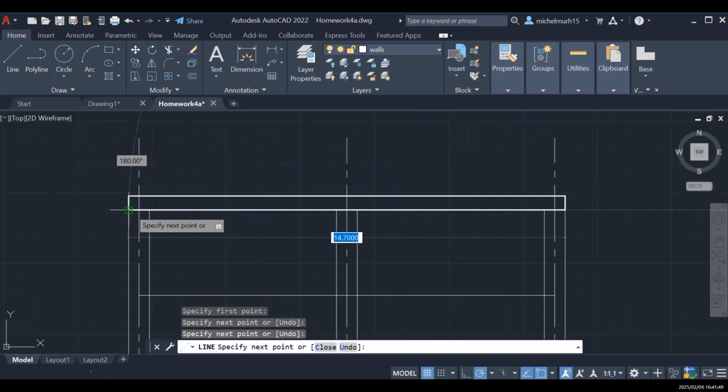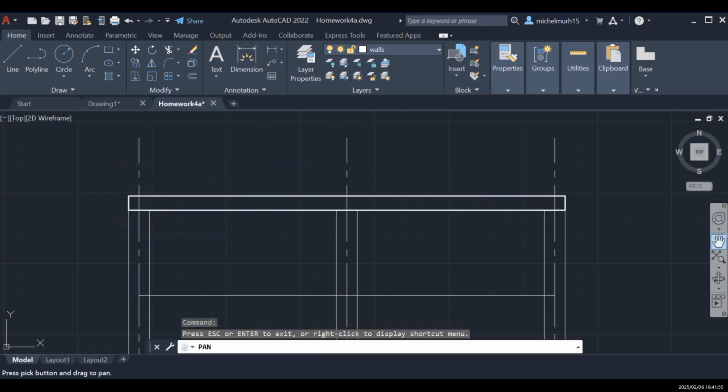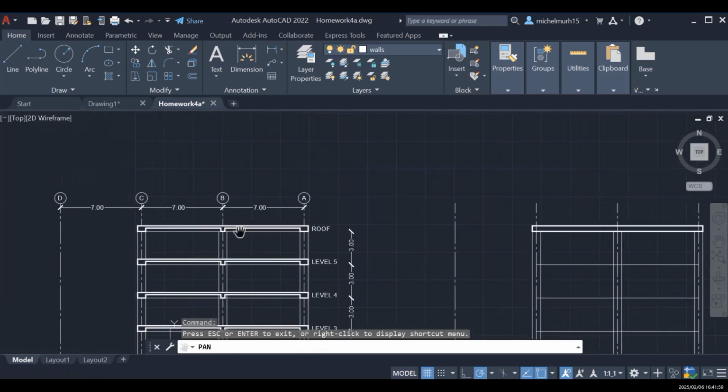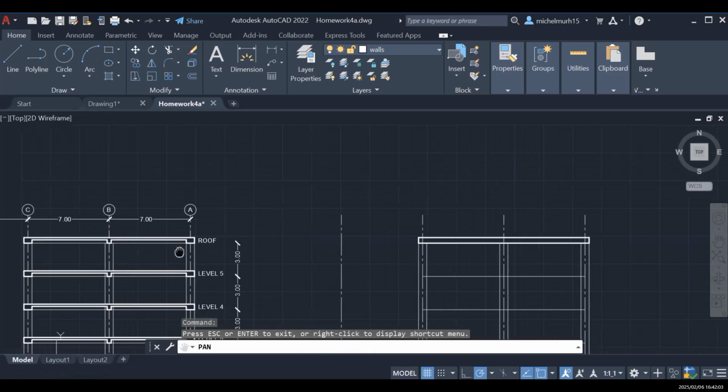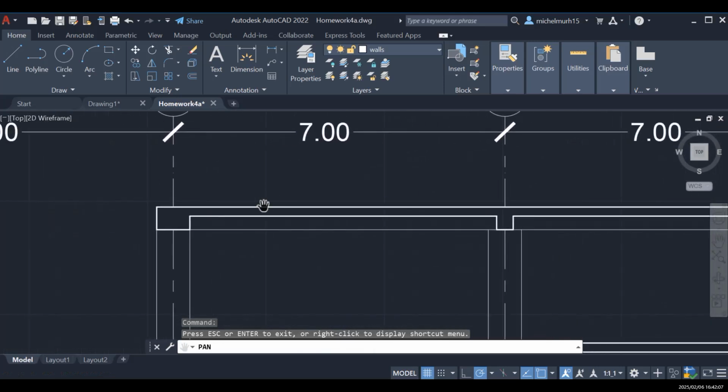But I know that there's something straight in the middle that I need to trim, so I'm gonna just put a straight line like this. But as you can see in the middle, we have a specific angle, a specific change that you have to observe here, right? As you can see, the inner thickness, let's check first of all how much that is. From here to here we have 0.2.